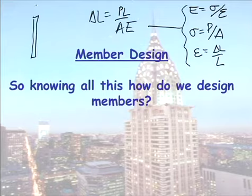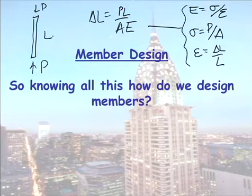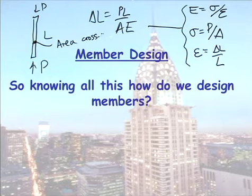If we have a member that is experiencing an axial force, be it tension or compression, and that member has a length of L, E is its modulus of elasticity, A is the cross-sectional area, then we can work out how much that member stretches or squashes.